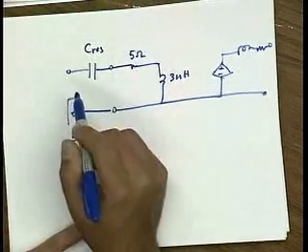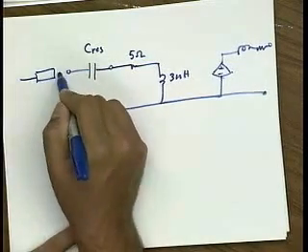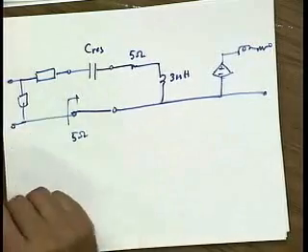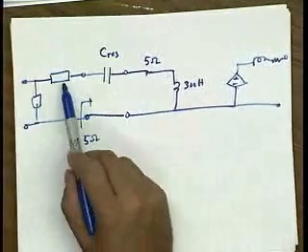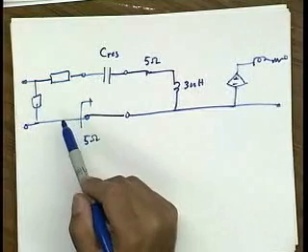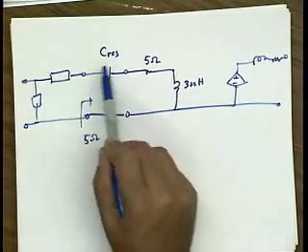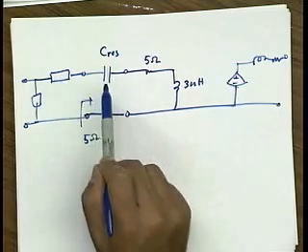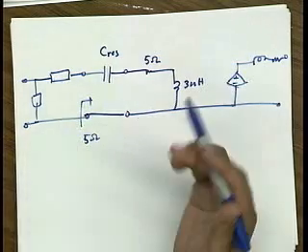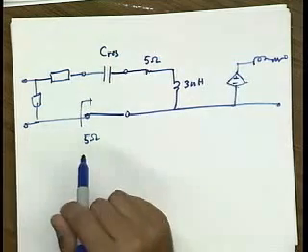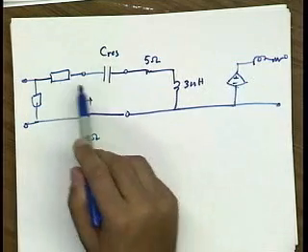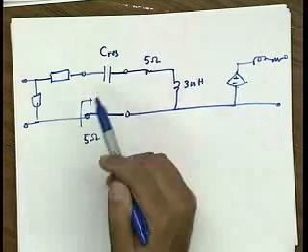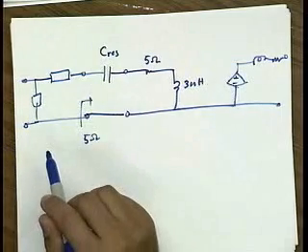So in an L matching network, I'm going to have an element here and an element here to boost the impedance. And I have a choice between using either an inductor here or a capacitor here. Now since I already have a cap here, it would be nice if I put another cap here, because then these two caps in series will give me an effective capacitance. And so then I have to use one less element. Or if I use an inductor here, this effectively would cancel out part of that inductance, so I'd have a new inductance. So either way, I can end up with a 2-element match.